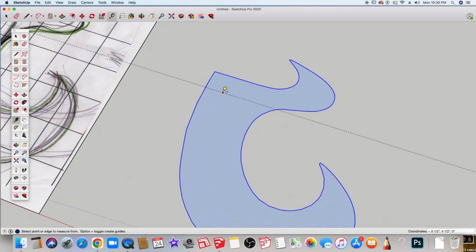I'm going to start my slot design in this area. The thickness of our material is 1/8 of an inch. So if this is going to be the middle of the slot, then I'm going to pull 1/16 to each side. To do that, I'm going to pull from the center on the red square and type in 1/16 and then quotes for inches from the middle up, and I'm going to do the same pulling from the middle down on the other side. So 1/16 quotes for inches, and now I should have a slot area, if I combine both of these, that is 1/8 of an inch.